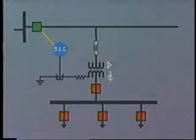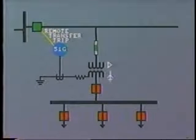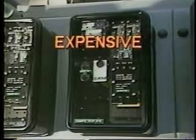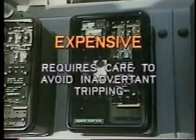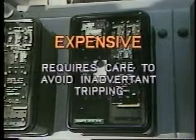One way of achieving this is to provide a communication channel between the relay and the breaker. This is known as a remote transfer trip signal transmitted over power line carrier or on a telephone circuit or microwave circuit. This method is quite expensive, and special care needs to be taken with the installation so as to avoid interference from outside signals which may cause inadvertent tripping. Of course, on large, high-voltage transmission lines, this method is used extensively, but it is not so common on distribution systems.